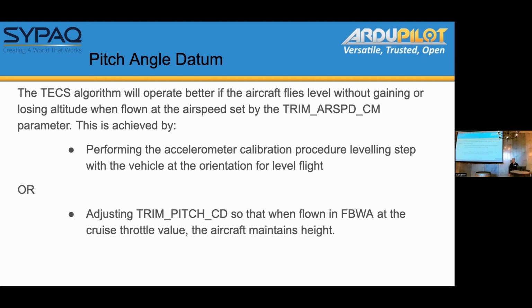But if you're somebody that's fastidious about setting datums up on your aircraft, I would recommend the second method. And just to back that up too, if you are running a quad plane and you want to set that datum for your lift surfaces, the angle of attack of your wing should be just a fraction positive versus those lift surfaces, but not too positive.